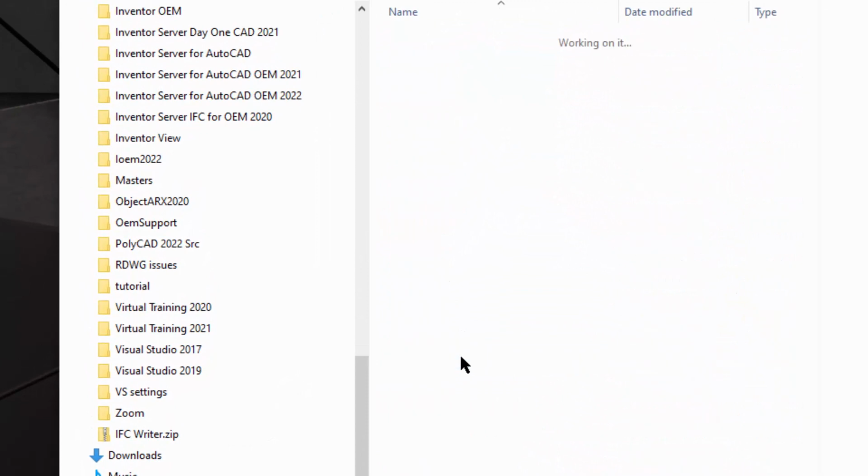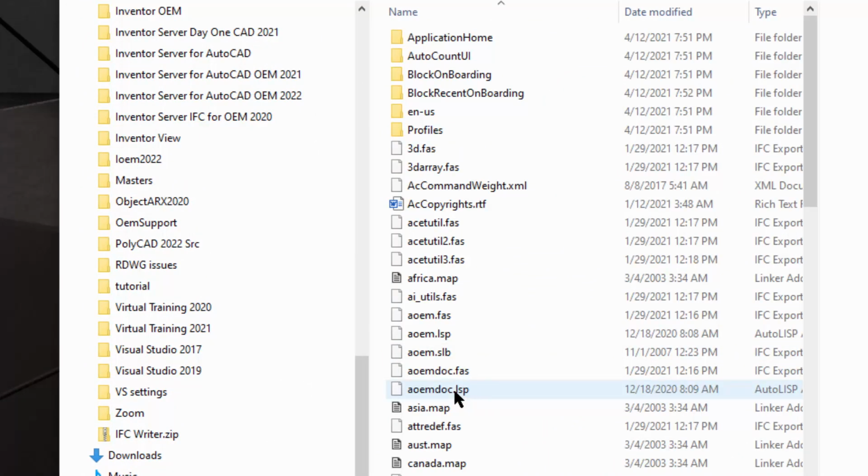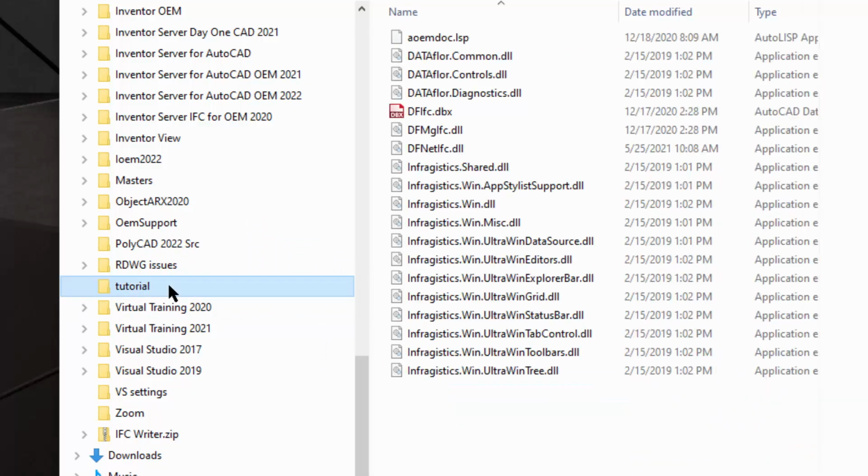As this is a new project from scratch, in other words, I don't have the startup function from before, I'll need to create the file and add the function to my host.lsp file. Make a copy of the AOEM version of the file.